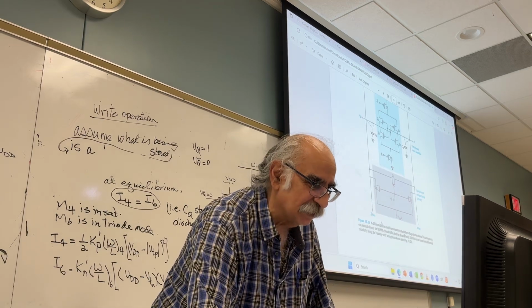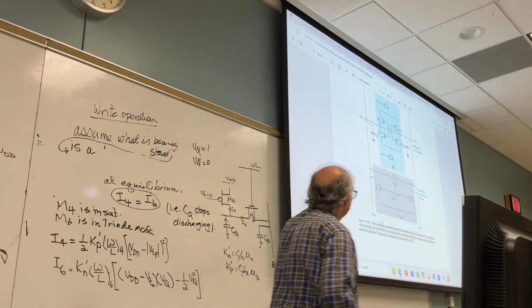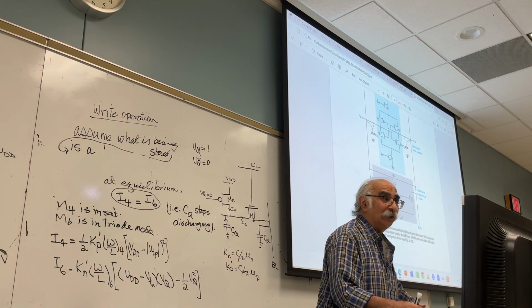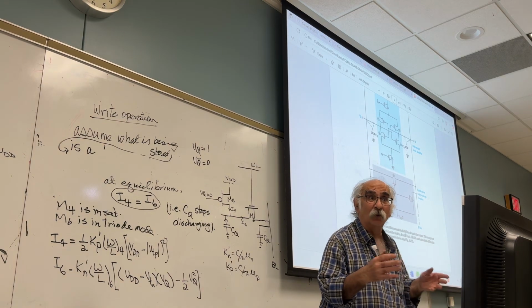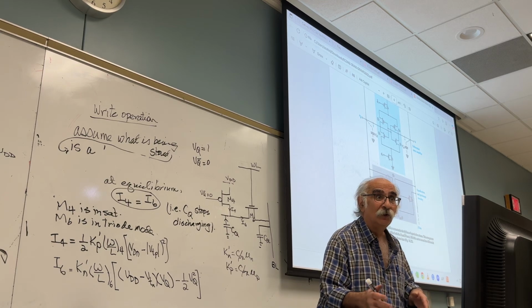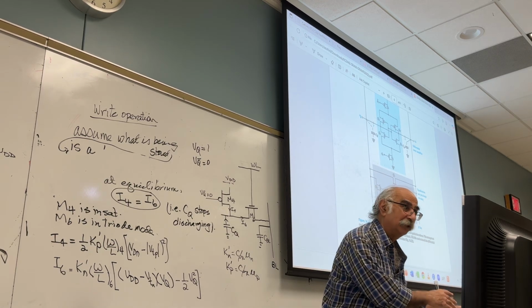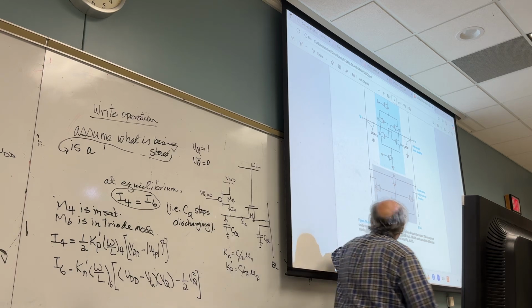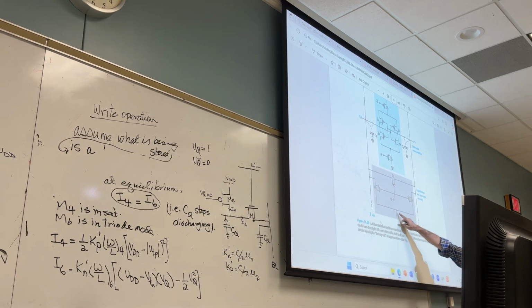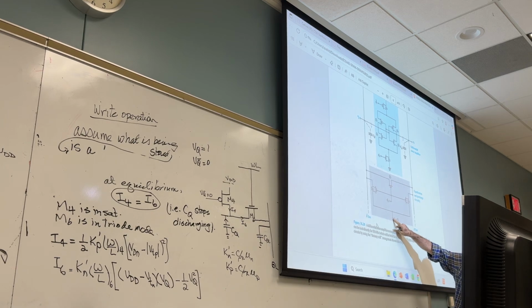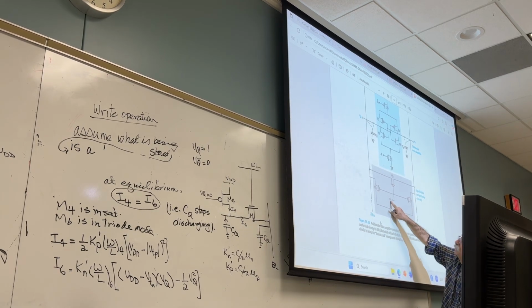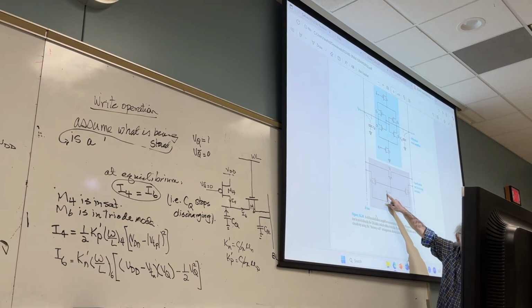Forget about the middle section. Look at the lower section. Pre-charge. What did I tell you a moment ago? You pre-charge both of them either to what? VDD over 2, all the way to what? VDD. In the diagram, he shows you VDD over 2. Let's see how he charged. This is VDD over 2. Yes. Connected to NMOS. NMOS. And there is a positive clock.